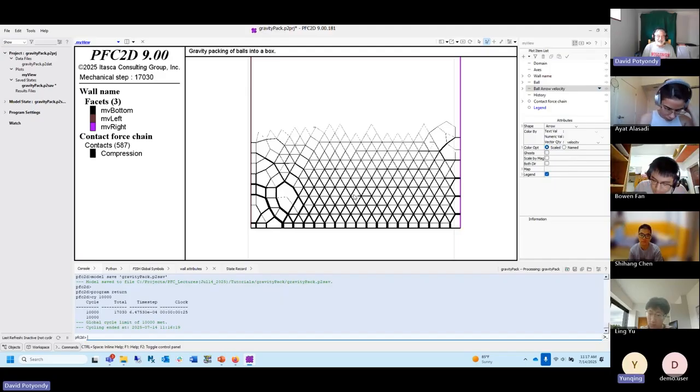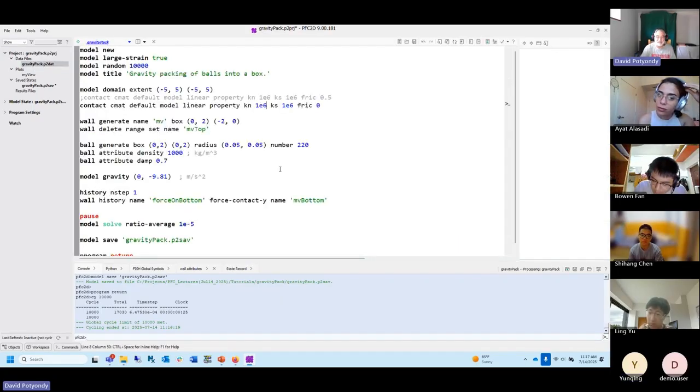Okay, because the only thing we might change is the stiffness. And if we run it again, it's going to be a whole different ball game of how it's going to behave. And it might not make it in 7,000. It might take more. Or if we change the size distribution, all of these things are going to affect how long it takes to reach equilibrium. So that's why it's really important to have this thing to give you a very good metric that in almost all cases will work, to know that you're in static equilibrium.